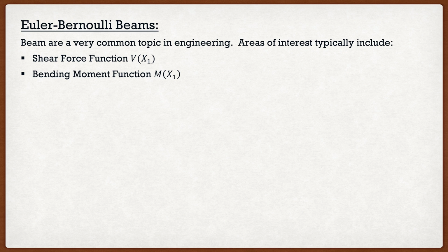Now, these are the two that are typically taught to engineers way back in their first year of undergrad because they're actually quite simple to analyze, quite simple to figure out what's going on with shear and bending moment. Now, let's say that you become a civil engineer and you get more and more interested in beams. Well, as you know, when we're designing beams, it's very important to design for shear and bending moment, but we also have to design for things like deflection. Of course, if you're designing a building and you're designing a floor located on some beams, but they sag a lot, so there's a lot of deflection, well, the occupants might not be very comfortable. It could withstand the shear and the bending moments, but if it's not very comfortable for the users, well, you don't really have a very good design.